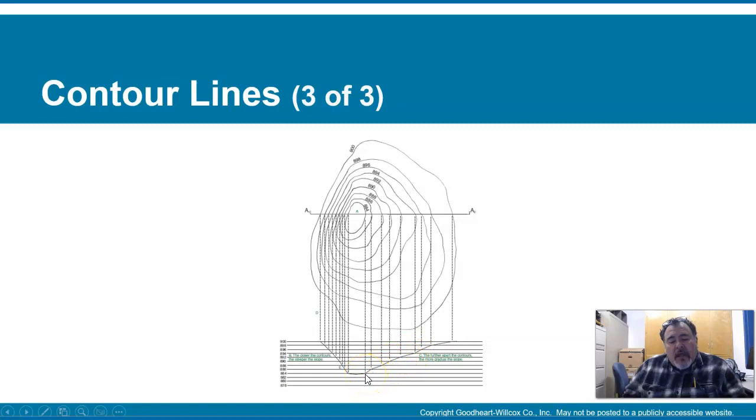So you go from one line to the other, and these rings show the change in the elevation and height. So you can see here that this is not an actual hill. This is actually a hole, or like a valley, right? You can see it dropping down and going back up. So that's how contour lines can show you the shape of the land.